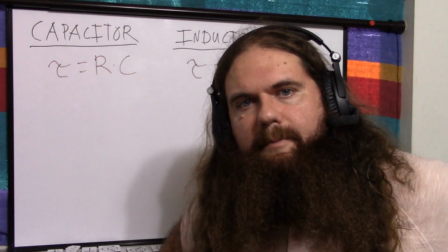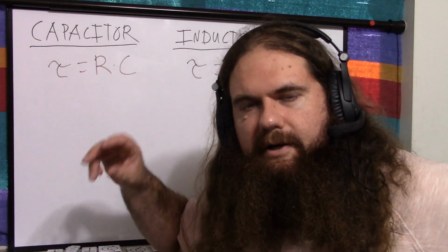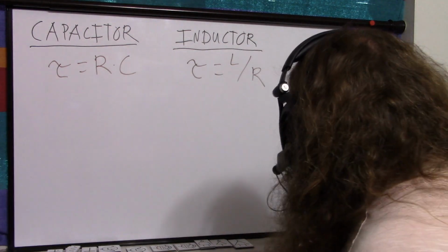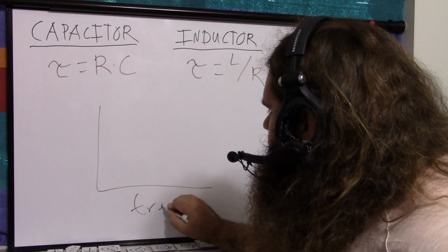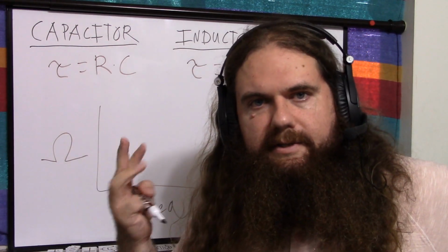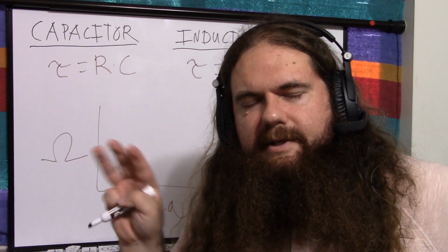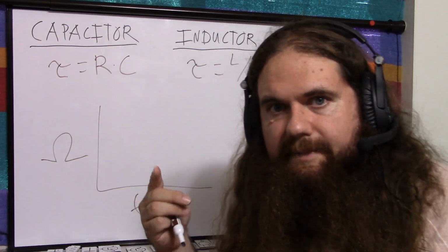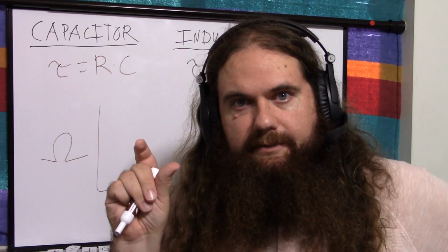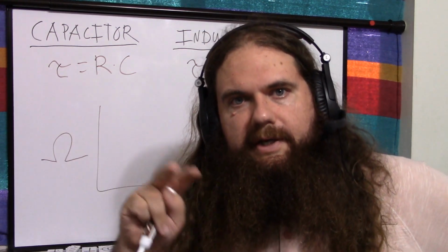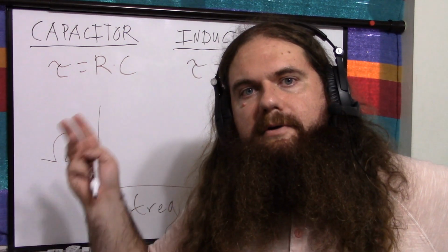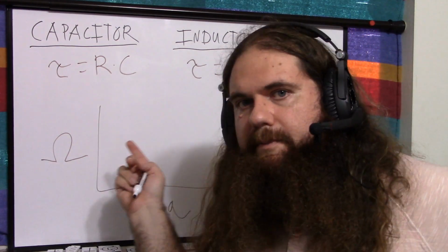And there's one more thing. You remember reactance? When we're talking about a filter, a capacitor acts as if it's a variable resistor. If you have frequency of a signal and you have reactance. Now, resistance, impedance, and reactance are all just ohms. The name comes from the context. Resistance means actually a resistor, or the resistance in a wire or something, like physically resistance. Impedance is usually talking about inputs and outputs, effective resistance there, and reactance is usually talking about a passive component acting as a variable resistor in this way.